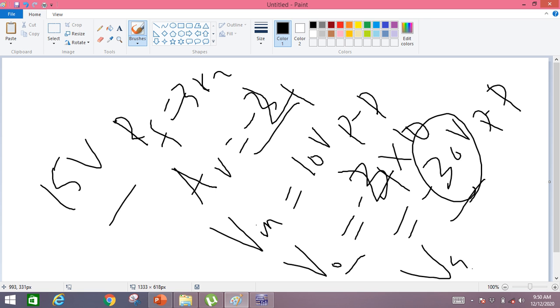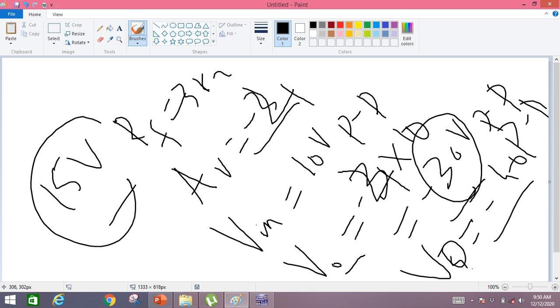It means that now if our gain is 4, the output voltage will be minus 40 volts peak to peak, or 20 volts peak. So if our output voltage is 20 volts peak, that is greater than 15 volts, our output voltage will get clipped at 15 volts because it will get saturated. So whenever we design the inverting or non-inverting amplifiers, we must look at the saturation point.